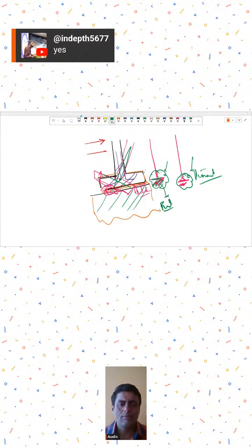So then, most of the engineers tell you that you may design your columns for both fix and pin, and then provide whatever is the worst case. This is also a practice that many people adopt, that they will analyze and design their columns, beams, etc. once assuming a fixed condition, once assuming a pin condition, and then provide whatever is the worst.